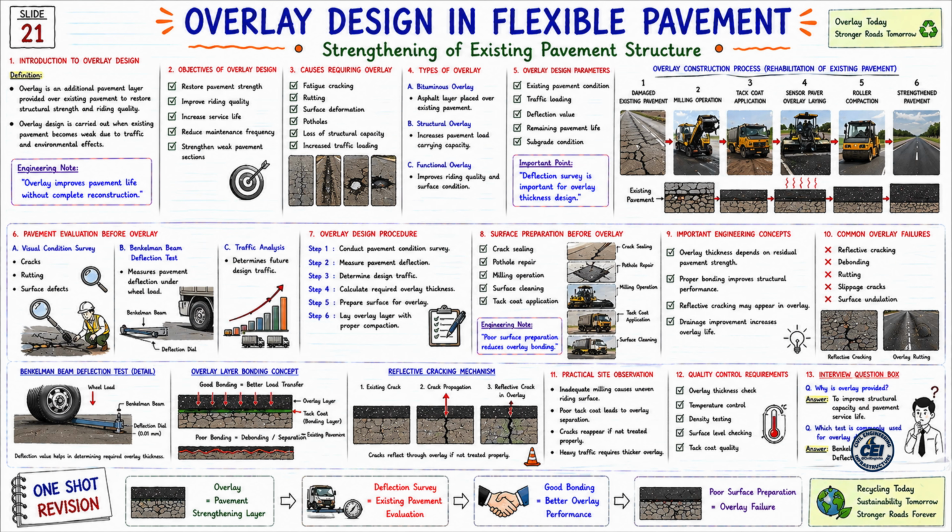Now let's see the interview question box. Q. Why is overlay provided? Answer. To improve structural capacity and pavement service life. Q. Which test is commonly used for overlay design? Answer. Benkelman beam deflection test.